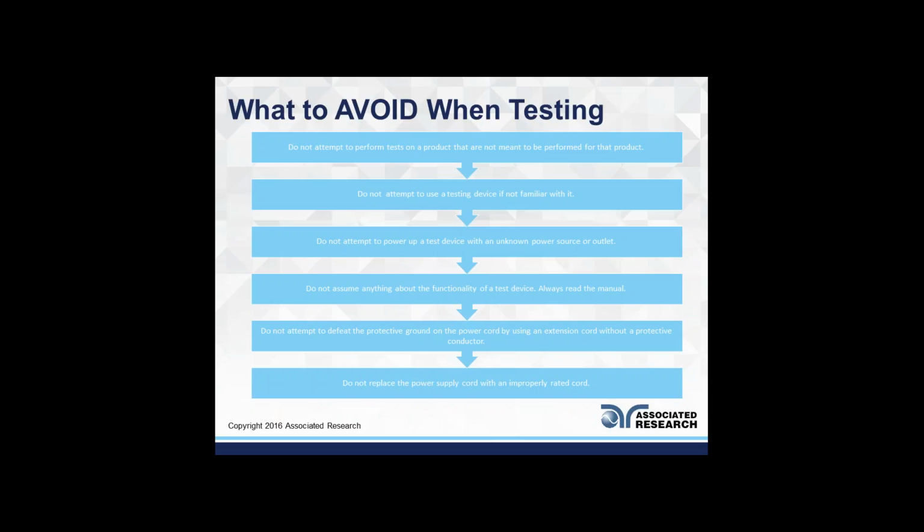If I'm using a ground bond tester that could output 60 amps of current, not knowing what 60 amps means, I would not want to be near that instrument. That's potentially a huge amount of current flowing through either a person, or your DUT could be damaged. So you want to make sure you're testing with properly rated voltages and currents, and that the instrument you're using is within its specifications.